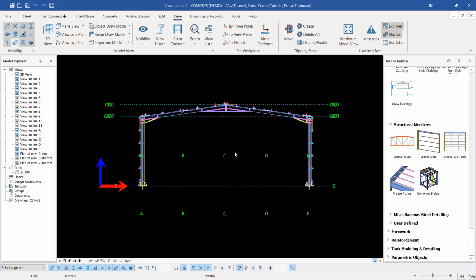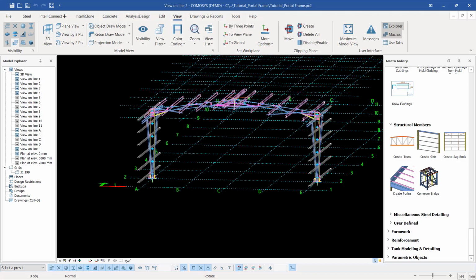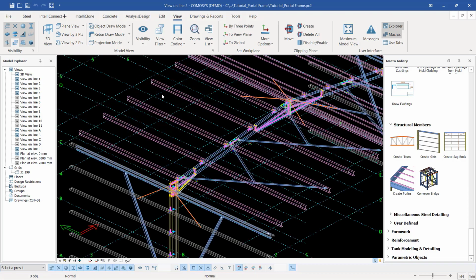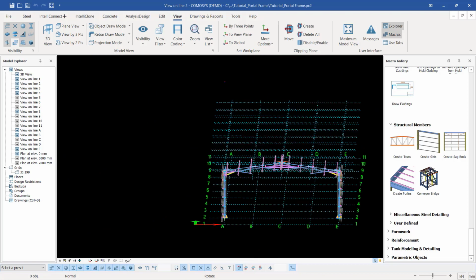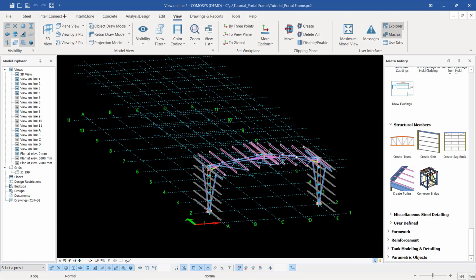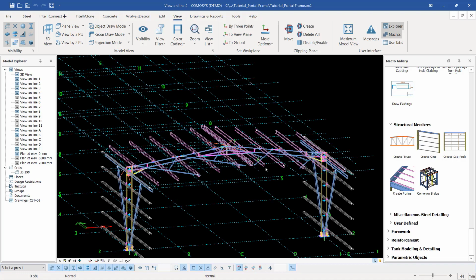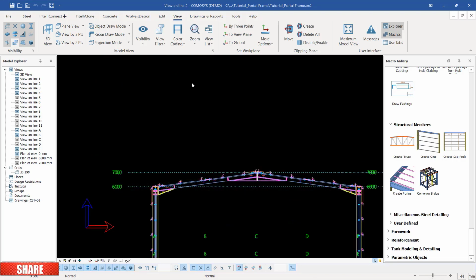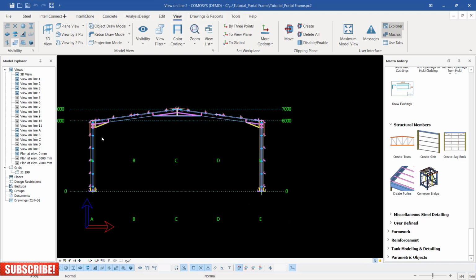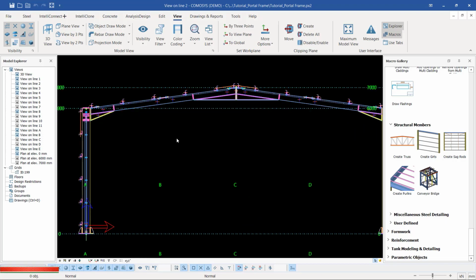Now, if I try to rotate this, we'll only see this side. So you'll wonder how to go back to the clear elevation that we had previously. Just double click on the screen and change all this rotation to 0, then click apply. The moment you click apply, it will revert back to its previous display, as it was prior to trying to play around with it.